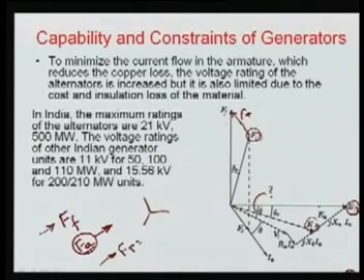So these two are related by another here, that is your XA multiplied by IA, and this is here you can say current, it is perpendicular to here, means it is a 90 degree. So what is happening is that we have a reactance here XA, and we have the leakage reactance of this winding in the generator.